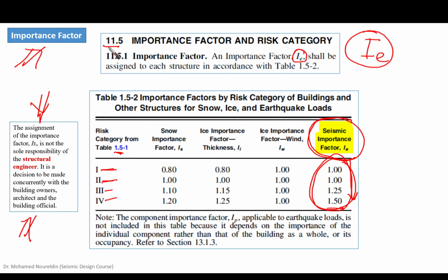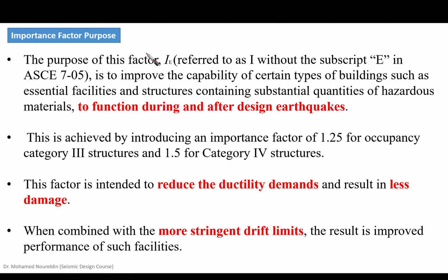Okay, so now let's go: what is the importance factor all about? Why do we need the importance factor? Actually, the importance factor is to improve the capability of certain types of buildings, such as essential facilities and structures containing substantial quantities of hazardous materials, to function during and after design earthquakes.